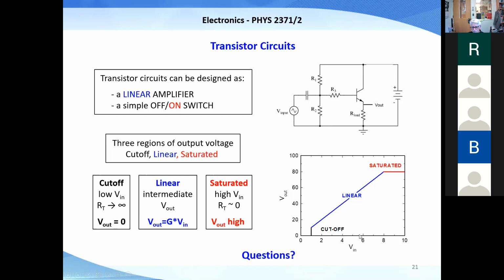So if you're singing a musical note going from 4 to 6 volts up here, your 4 volts would translate into 40 volts, and your 6 volts would translate into 60 volts. So as the microphone went plus or minus a volt, the speaker would go from 40 to 60, 20 volts.